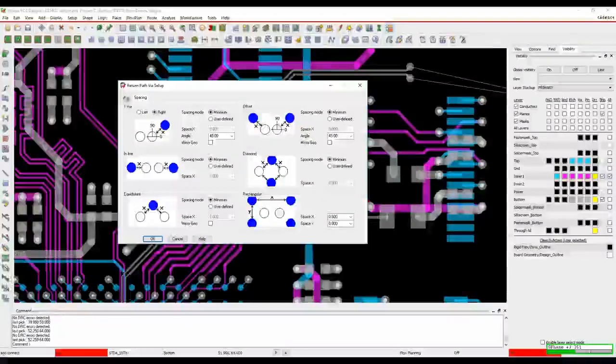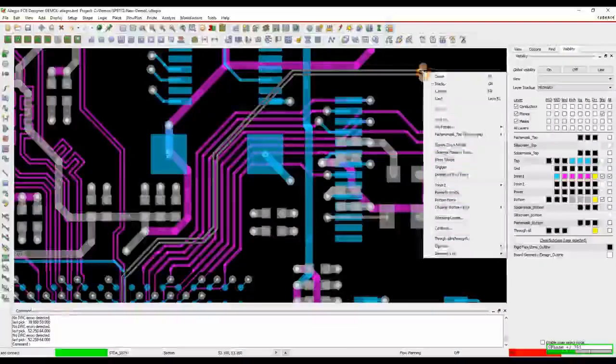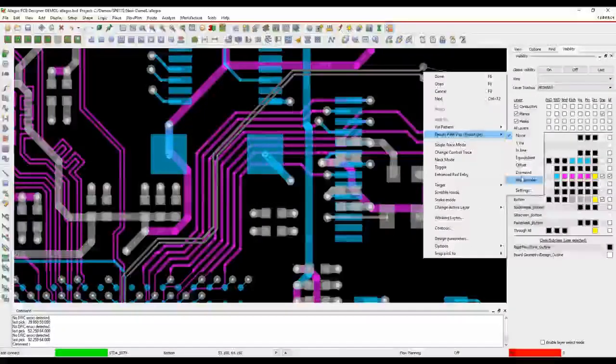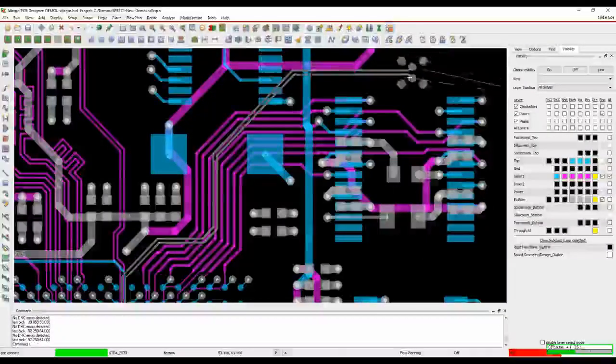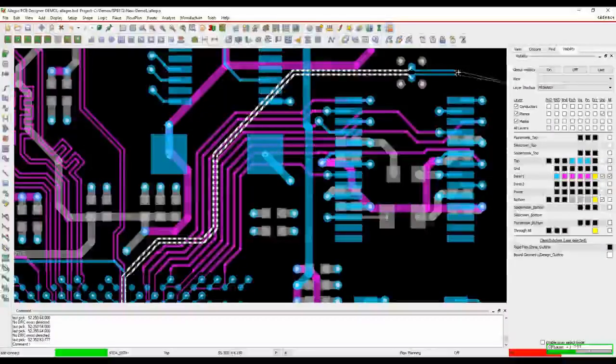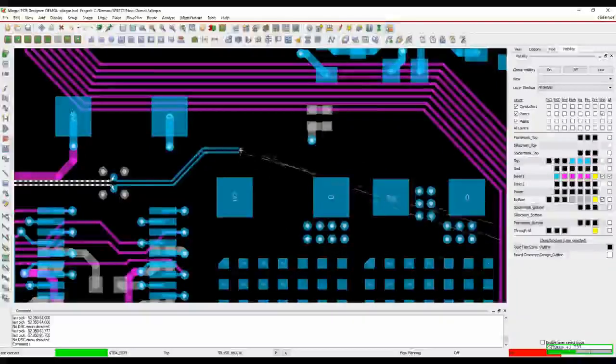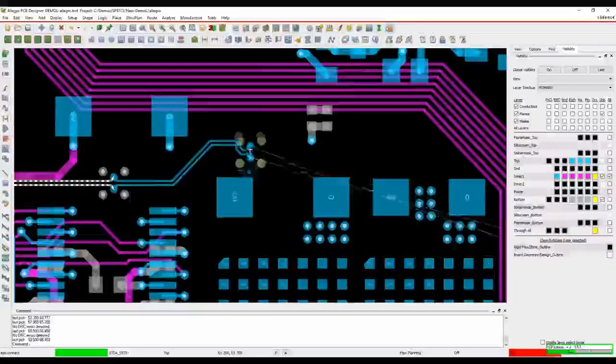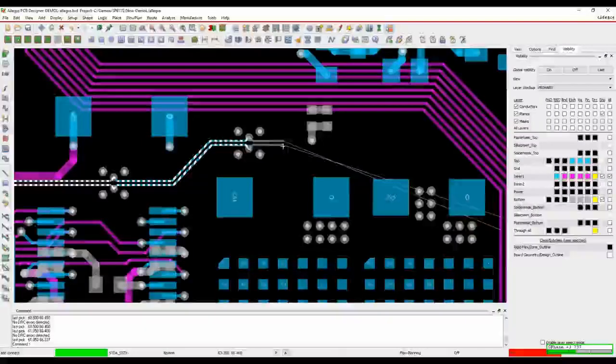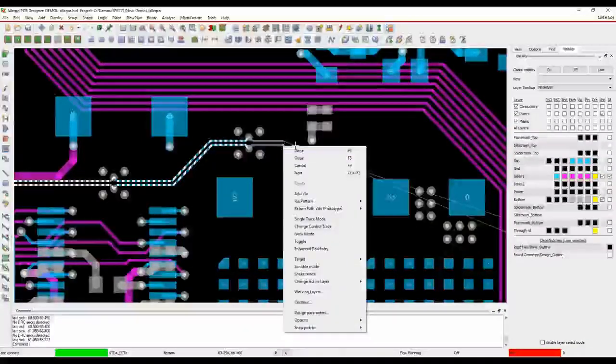So in this example what I'm going to do is leave the settings as they are. If I go to the return path vias prototype and we'll do a rectangular, you can now see how effectively I get my return path vias added when I add my vias. And we'll just do a double click again just to show you this. So let's come up to here, we'll double click again to add our vias, and you can see my return path vias are adding at the same time I add my default set of vias, which can be really helpful when you're doing your differential pair routing.